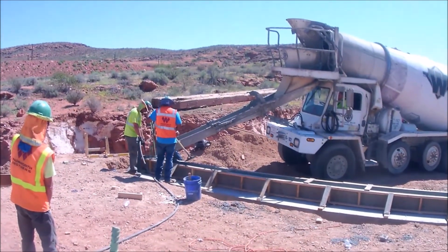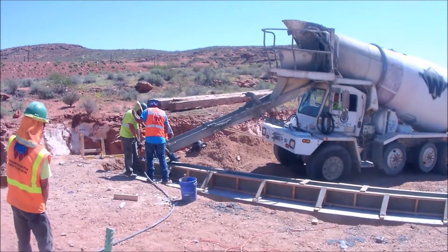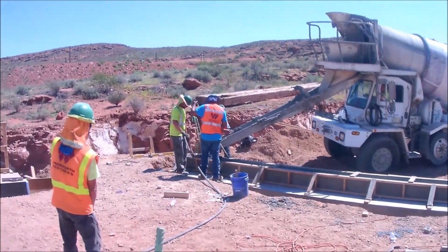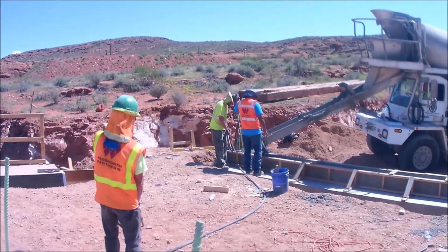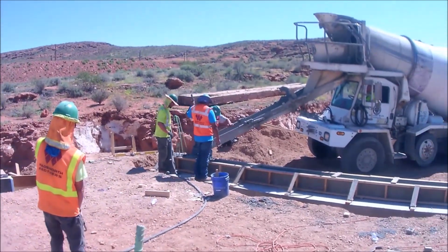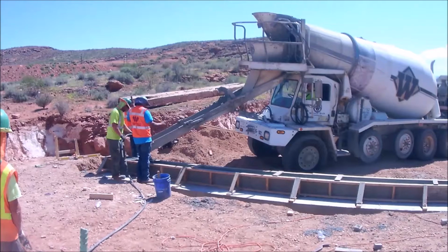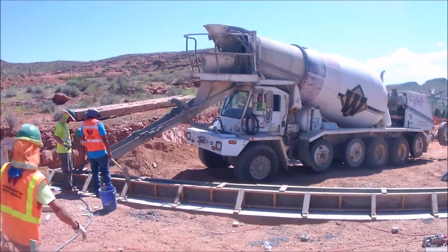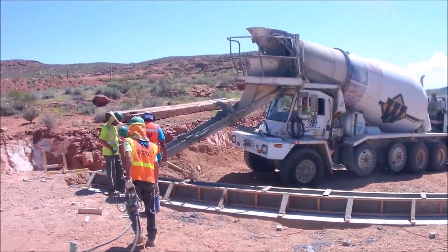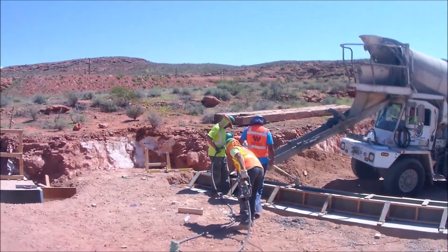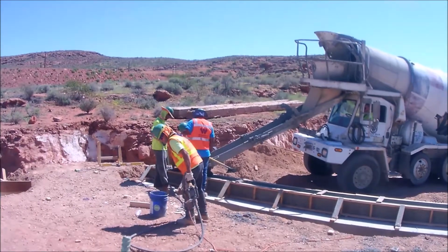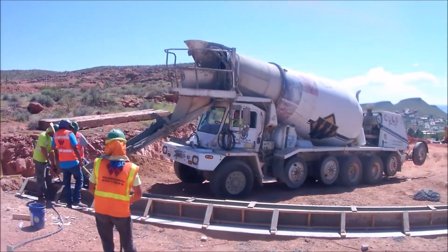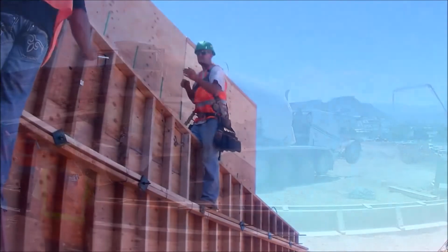Placing concrete creates the hazard of concrete burns. PPE will include mud boots with taped tops for deep concrete pours, latex dipped gloves, safety glasses both day and night. Our concrete pavers and bridge deck finishers use augers. Fall restraint will be used on paver rocket launchers. Daily safety briefings will make workers aware of the augers.